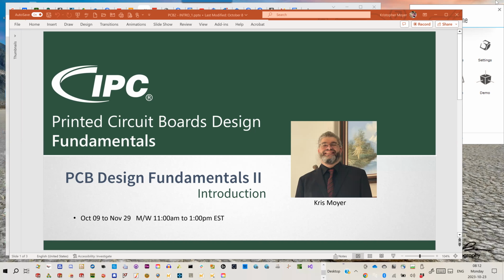Deleting the rooms is a personal preference after you've done your placement. My issue with that is every time you delete a room and then you have a revision update, where I need to make a change to my design, I need to change a resistor or add an RC pole to something, every time you do an update from the schematic, it's going to try to put those rooms back in anyway. So instead of deleting rooms, I simply make them invisible. I turn the little eyeball off so they're no longer visible, even in rooms with repeated. After I've repeated the room and placed them where I want them, and I'm going to do my main board routing, I just make the rooms invisible.